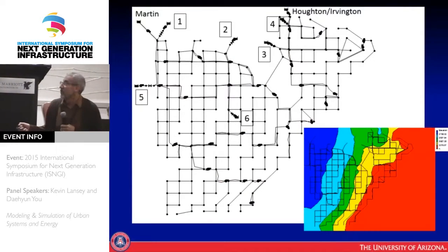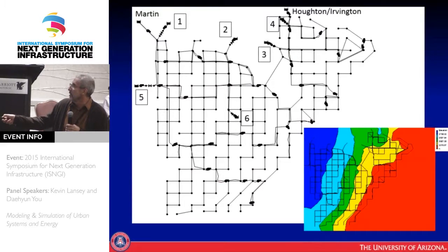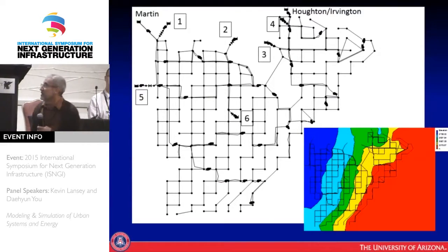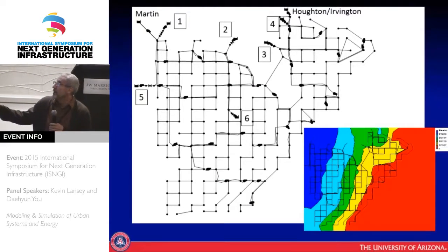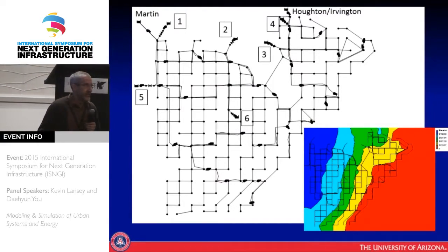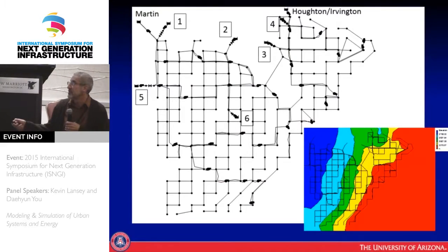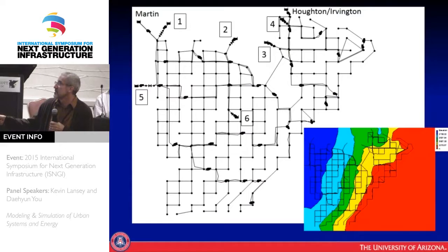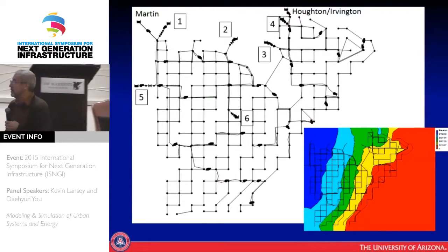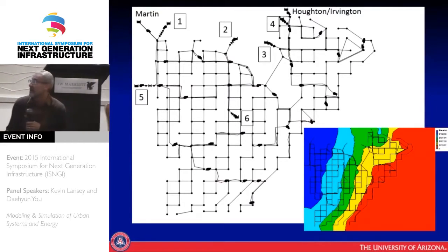For the water, in terms of water supply, this would be what our network would look like. Our elevation is increasing down to the southwest. So we have lots of pipes in here. It's around 500 or 600 feet difference in elevation, which means we have to have lift stations to be able to pump the water up, and that's what these things are here, lift stations. The 1 to 6 are those wastewater plant or satellite plant potential locations that I mentioned a minute ago.